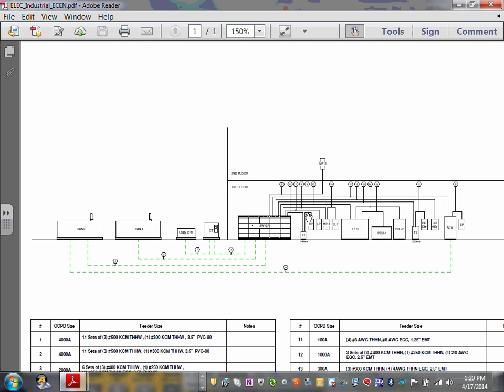The bigger the system, the more you specialize these panels. And to add salt to injury, we need to back up the system. So we have two generators here sitting, going underground and going to the switchgear. This is an ANSI arc switchgear, the highest that you can get, so we can parallel with this switchgear.